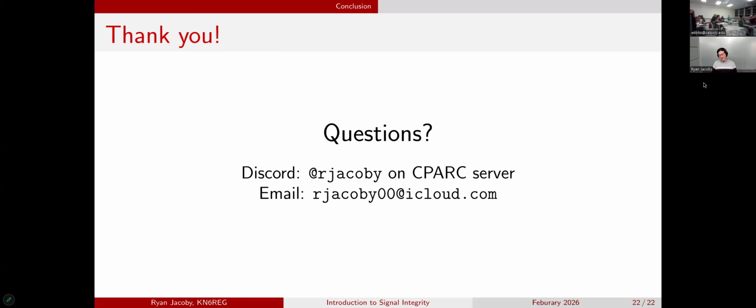Generally, you want them to be as big as you need them to be, and generally the bigger the better. Bigger in capacitance, smaller in physical size. The two things do contradict each other. So oftentimes you want to look to the data sheet of whatever device you're using for guidance. Like in the STM32 example I gave, ST gives you in their data sheet the recommended decoupling network.